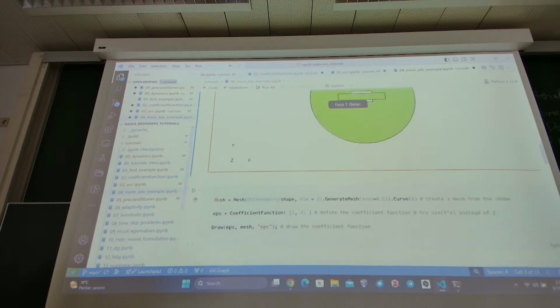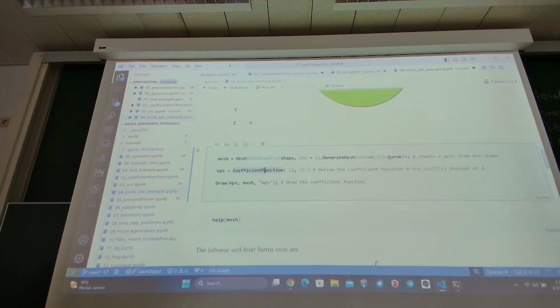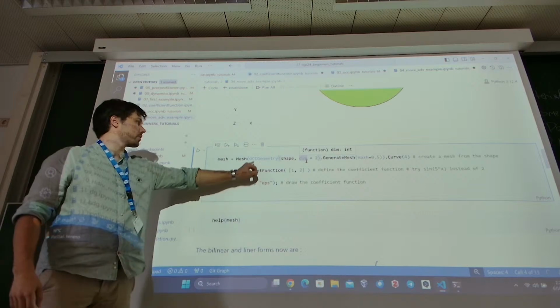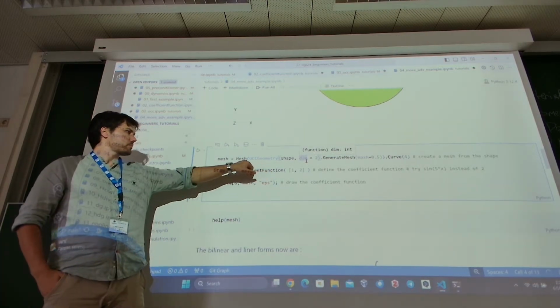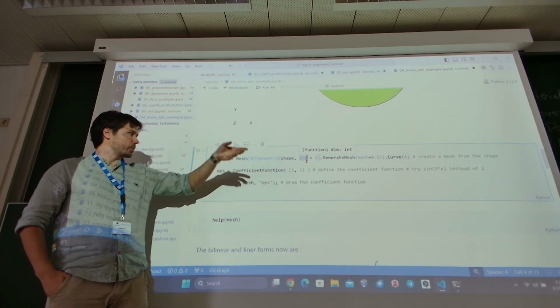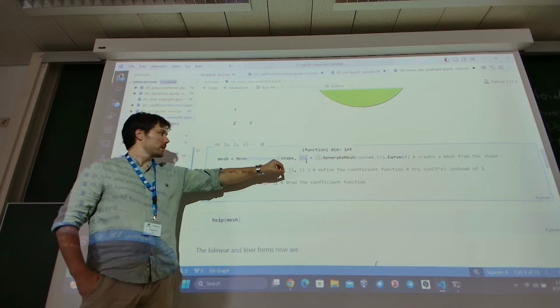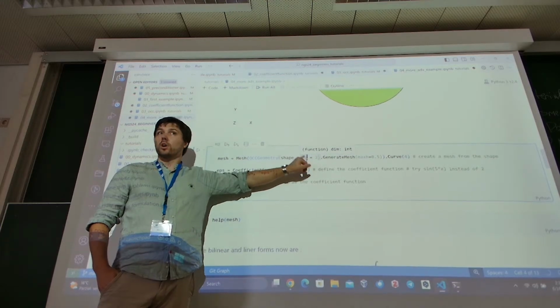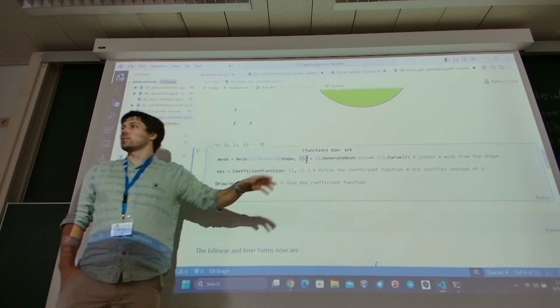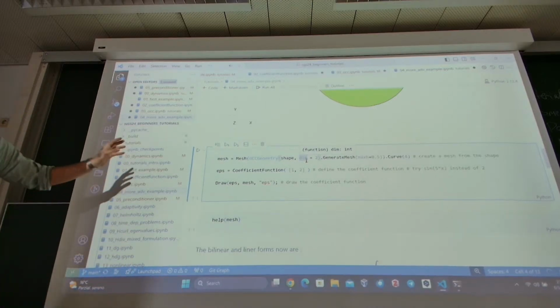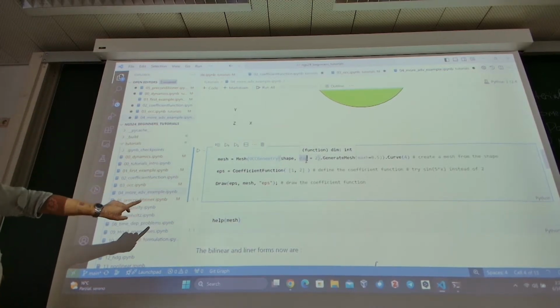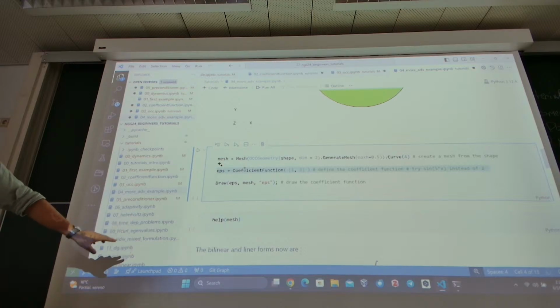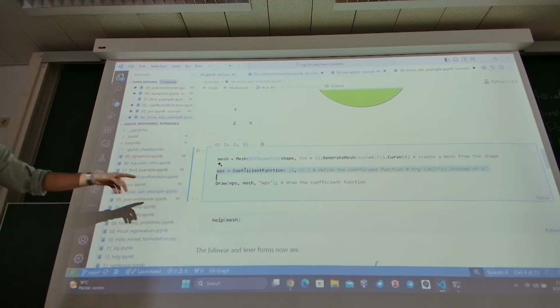Okay. All right, now what we do is, obviously we create a mesh, we pass to using OCC geometry. One thing that is a pitfall in general is that when you create a mesh from OCC to NetGen, you use OCC geometry shape, and you need to specify the dimension. If you don't do that, in this example, you can see that something wrong is going on. So please do it. This is not correct. Sorry, I forgot to change this.